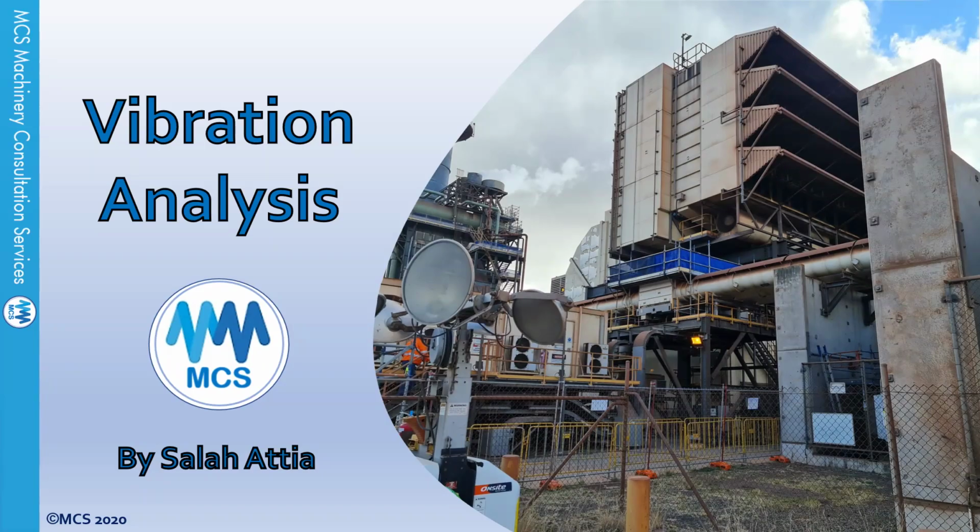Once this event starts to develop, it will excite the lower frequencies, and it will appear easily in the lower frequency range. Normally the bearing fault frequency is the same. For example, if the outer race is 75 hertz, this is the same frequency. But friction, noise, lack of lubrication, metal to metal contact, all of these events happen with very high frequency and very low amplitude. That's why we mostly see them in the high frequency range.